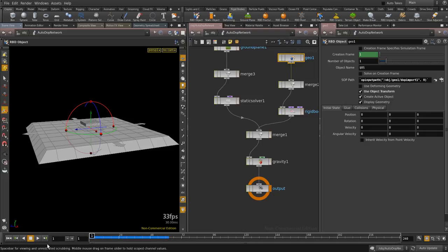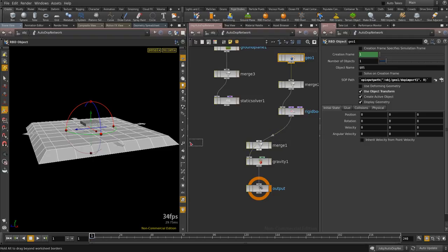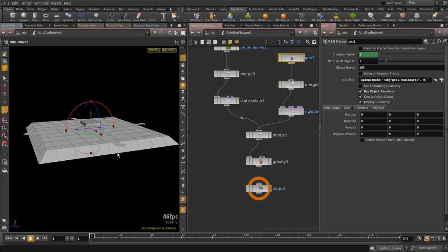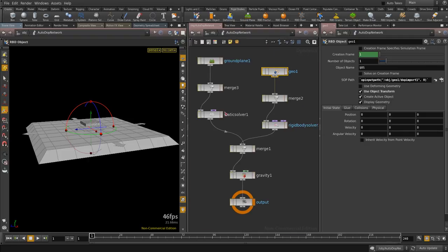We also see another very interesting aspect of Houdini. In the timeline, I have here the green line. The green line is the cache. Every time I create one simulation or change something, my cache is deleted. If I press play, Houdini calculates this simulation and caches it. So when I arrive at the last frame, I can also change my timeline, for example here to 100.